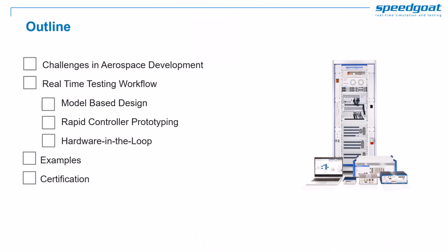To start, I will provide an overview of the challenges we face in the aerospace market when it comes to the development and testing of controllers. We will then examine the model-based design workflow required for successful real-time testing and quickly cover rapid controller prototyping and hardware-in-the-loop testing concepts to ensure that we are familiar with the most important concepts. Throughout the webinar, I will provide examples to illustrate how these concepts look like in real life. Finally, I will highlight how model-based design can assist with validation and certification, which is crucial for most aerospace companies.